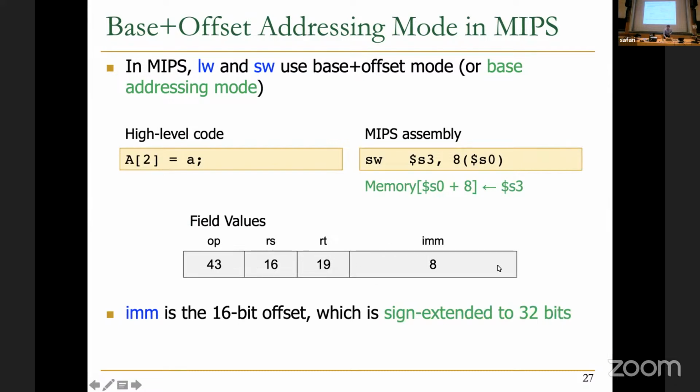Yeah, this is the 16-bit immediate over here. And so you can see that we actually set it to 8. So it's sign extended to 32 bits, very similar to what we did in LC-3, where we sign extended the bottom 6 bits to 16 bits. The word sizes of the architectures are different. That's why this is 32 here and 16 in LC-3. Okay, hopefully that makes sense.